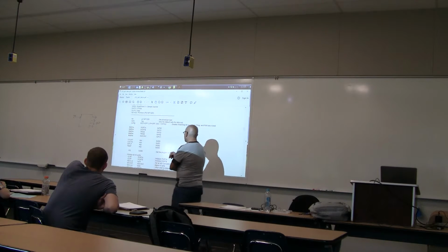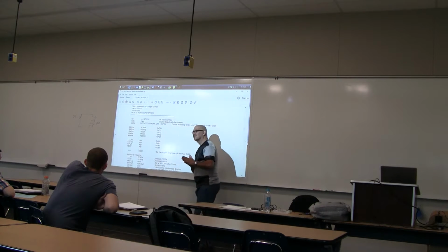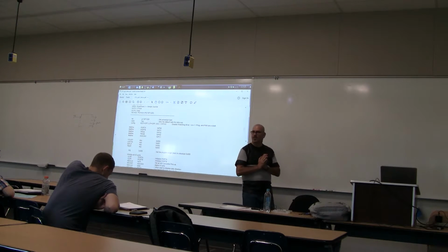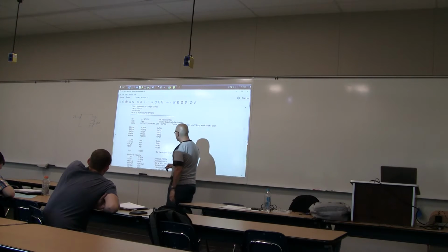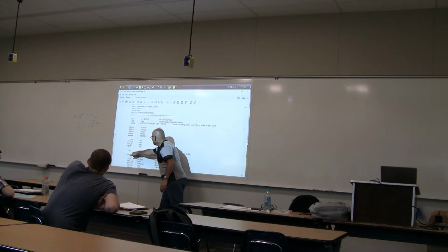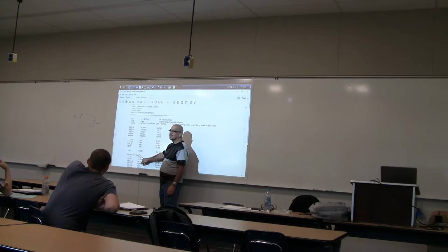And then org, we're going to write a bunch of assembly language code. And it's going to create ones and zeros that get stored in memory. We have to tell it where should we store this in the program memory. Since the system starts executing instruction 0, we want to make sure that our first instruction is stored at location 0. That's what this statement does. Okay, this says the origin of the program is location 0, and now the first instruction I write goes to location 0.